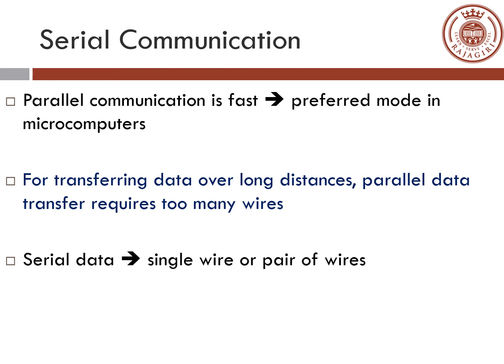Parallel communication means we're sending out the entire data word that's being put out by the microprocessor. So in the 8085, we will send out the data bits D0 to D7, 8 bits in parallel. This would be the preferred mode, and it will be much faster than sending it out serially. Within the microprocessor system, we would connect the microprocessor and the I/O devices like a printer or a disk for short distances using a flat ribbon cable and parallel connectors.